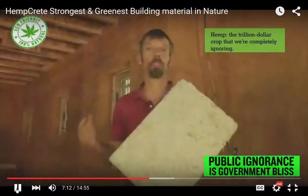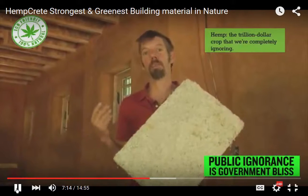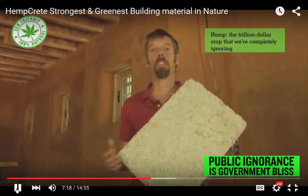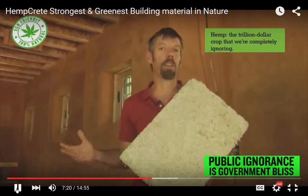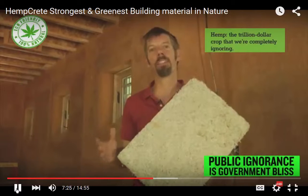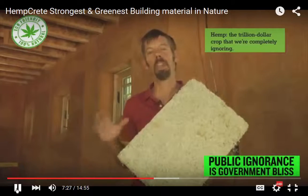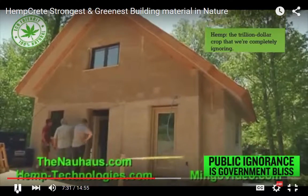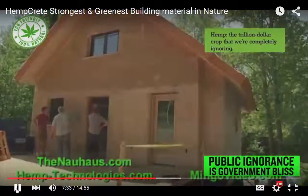So for example, in our house here, the Now House prototype, since we're trying to get to such high energy efficiency levels, we have a 16-inch thick wall to get us a performance rating of R40. We could also do a 10-inch wall. So we have flexibility in terms of the amount of insulation that we're going to use with the exact same procedure for construction. That's fairly unique in the world, and it's another reason why Hempcrete's a really great product.